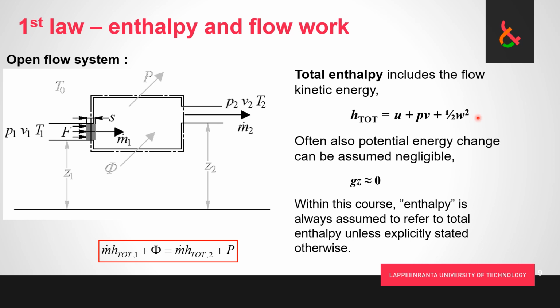So what happens at the surface of the temperature sensor? The flow velocity exactly at the surface is actually zero. It means that all the kinetic energy of the flow at that point was converted to something else, and the something else is specific internal energy. And that means that temperature has increased, and that means that this is the reading that we're actually going to get.